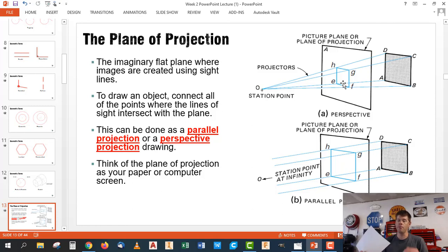Okay? In parallel projection, since we discount depth perception and throw it away, your drawing in a parallel projection environment, like the bottom one down here, what we use as engineers, is always perfectly scalable. We might scale the entire drawing up or down by a ratio, but if I take a measurement off of my drawing, I know that I can always scale it in some way back to the original object.